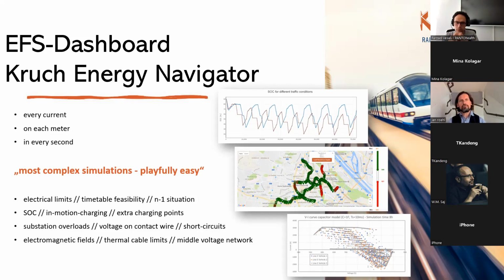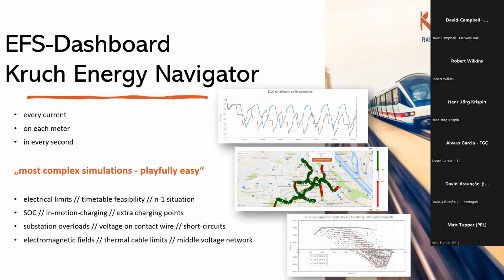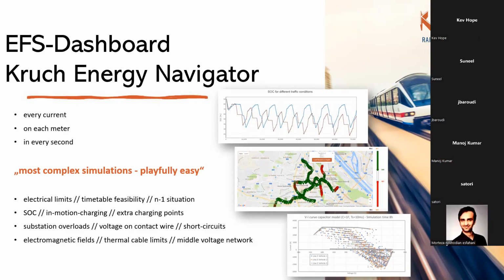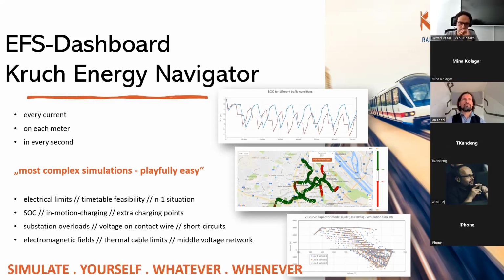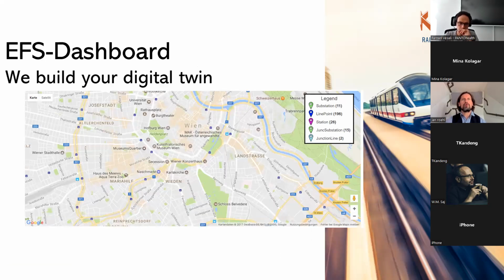With our simulation tool, you can put in the question in the evening. You just change the settings as you want them, and you press simulate, and after a few hours you have the results. And like this, you will very playfully test what the limits are, how you can improve your network, and you can do that all by yourself. When are substations overloaded? When is the voltage too low on the contact wire? What delays will I get in my timetable by doing that, and so on. All the results are presented in a graphic way, very easy to understand and very easy to apply.